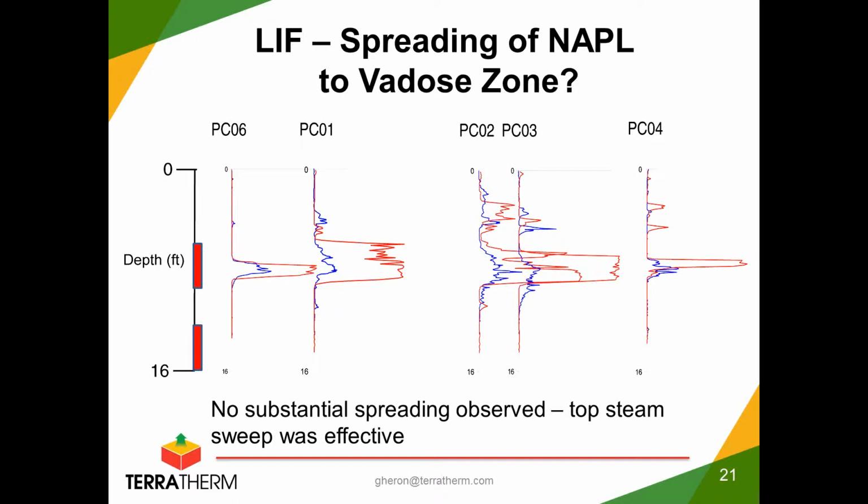and by the pumping in the middle where we created a drawdown and then pulled the NAPL to the well, we might actually have moved it maybe 1 or 2 feet down. We may have a little higher signal than before, but that's a relatively small price to pay for getting your 520 gallons out of the ground and all of your TCE removed from the source area.